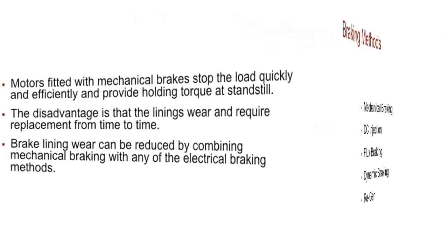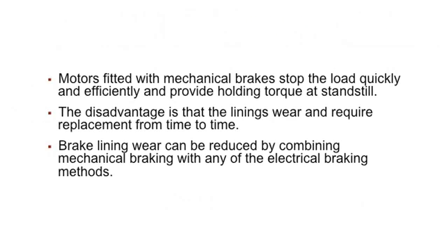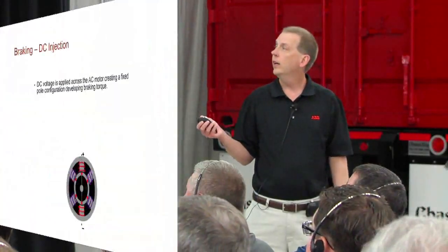First off, there's mechanical braking. This is the most straightforward braking. There's a brake on the motor. All you have to do is tell that brake when to engage, and it'll stop the motor, and the drive doesn't have to do anything, right? And all that energy goes into heat on the brake pads. So that's a simple one, just like your car. No problem there. The drive has actually control logic to sequence on and off that braking contactor. So you could hook it up to some of the digital outputs on the drive and control the mechanical brake on the motor. But if the motor doesn't have a brake, there's still some options.